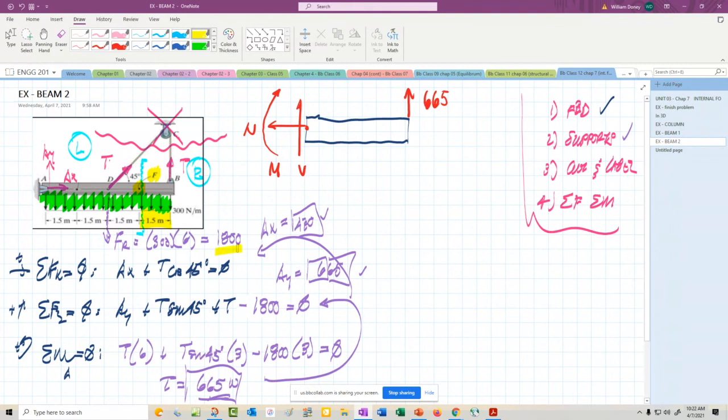Now, the whole thing is 1,800. That means half of it over here would be 900. Same here. And then half of that would make this 450 in here. And we put that as the center, so we're going to have 450 acting downwards. Very okay with that. We have to include that distributed loading. We found the resultant originally just to help find reactions, but once we go back to the cut, we have to include that there. That is the 450 that I have written right there.